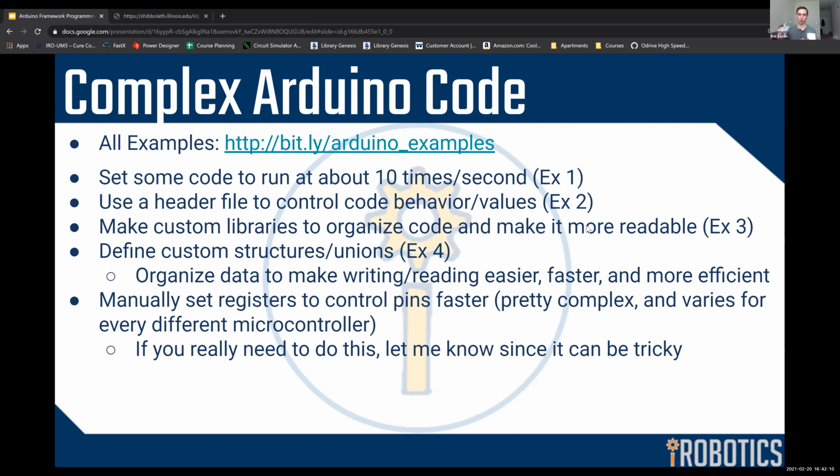Those values you might want to store in your Arduino so that whenever you program it again or turn on the Arduino, it's already ready and has all that, so that they'll all turn on at the same time. You can put all these little offset numbers packaged together in one structure, like motor 1 offset, motor 2 offset, motor 3 offset. Then you can take that whole thing and write it to your EEPROM or storage that exists on the microcontroller. And whenever you want to read it out, you just read it into the structure. Then you can say, what is motor 1's value, motor 2 value, motor 3 value.